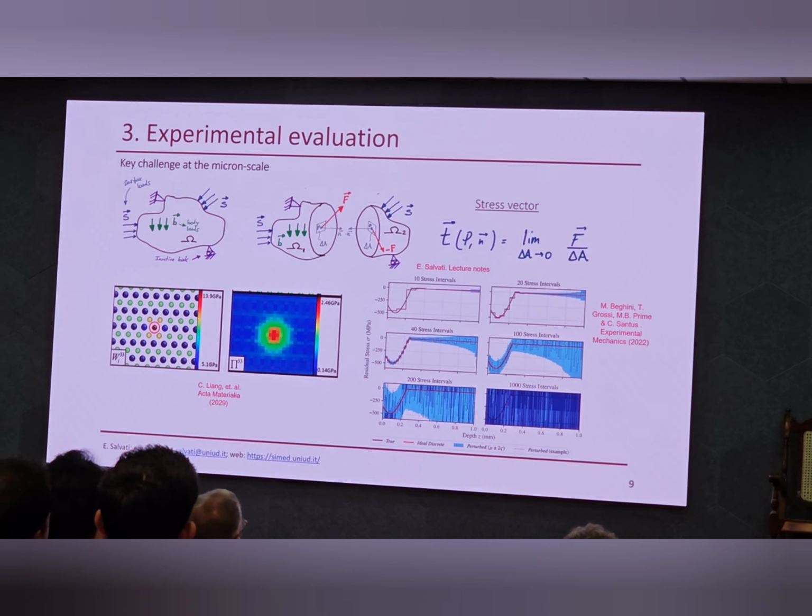Another technique which I contributed a lot to during my PhD was the ring core method. Essentially, it relies on the same principle, at a different location within a ring. And as I said, you can also get depth profiling, and also this alpha here represents the principal direction. So you can also get the principal direction from this technique. Good.